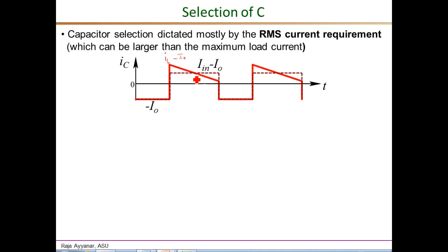That is this red waveform, and we are going to approximate this at least initially by a pure square wave current. In the on interval it's exactly the same as the complete current wave shape, and during the off interval it is approximated by a straight line of value equal to the average of IL, which is IN, minus the same load current IO.